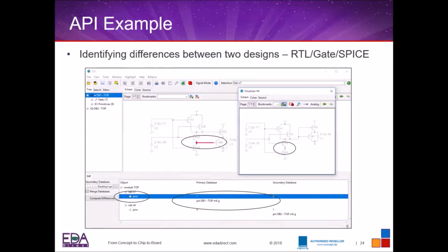So this slide, what I'm illustrating is there's two examples. In this case, it's an AND gate, and there's a net reported in red, net reported in green in the second visualization window. And you can see that in this case, this net in red fans out to 3 objects, whereas the net in the second case only fans out to 2. So in this case, we're doing a net by net comparison in the design.